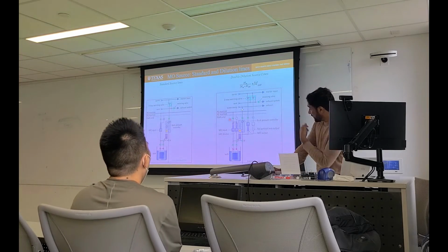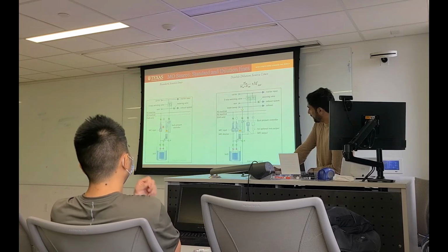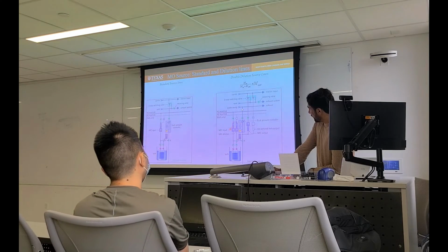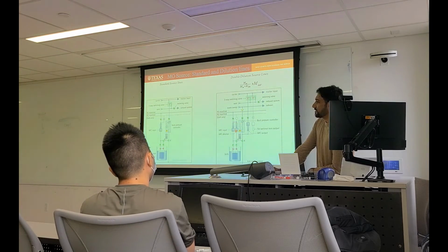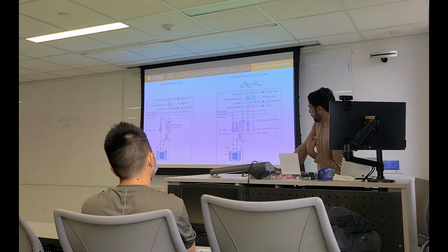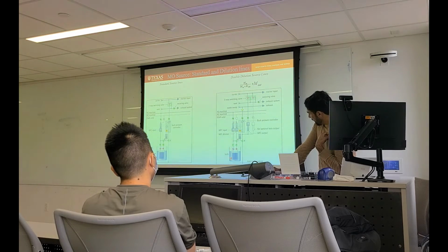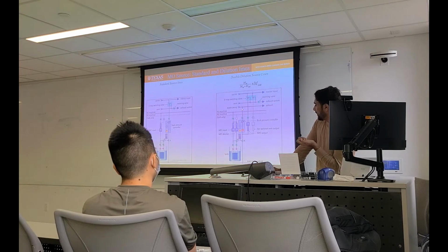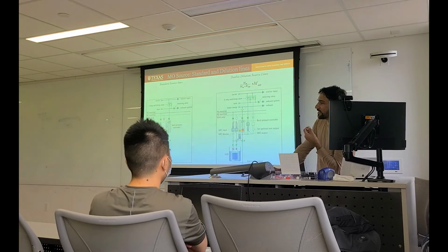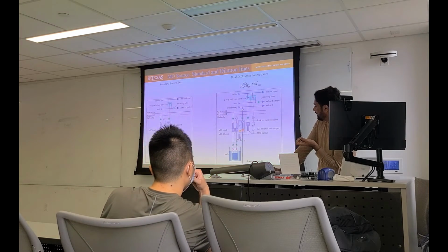In the double dilution source line, you have one input MFC here, and then an additional MFC just as the dilution line. You carry your source and dilute it, and then pass it through the electronic pressure controller. Now, suppose you want 20 SCCM, but the total flow after dilution is 40 SCCM or 30 SCCM.